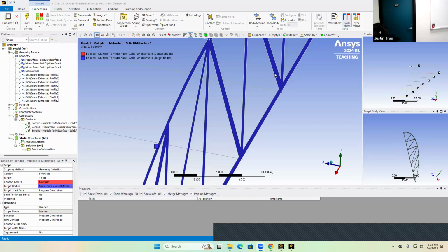That looks good. Then we connect the road and the beams. The road has to be connected to the side of the bridge, so that should be the method for the right edge of that road and the bridge itself. So that's the edge I would set as a contact, which is the target.